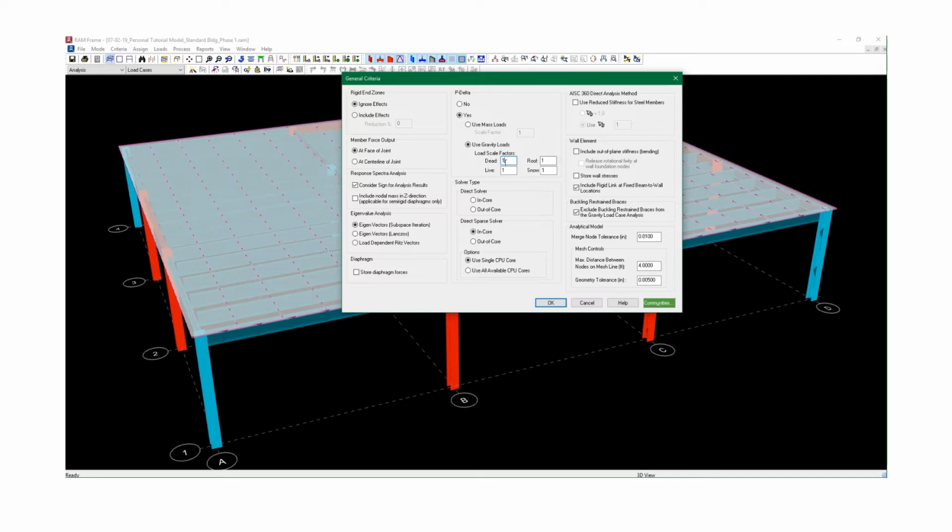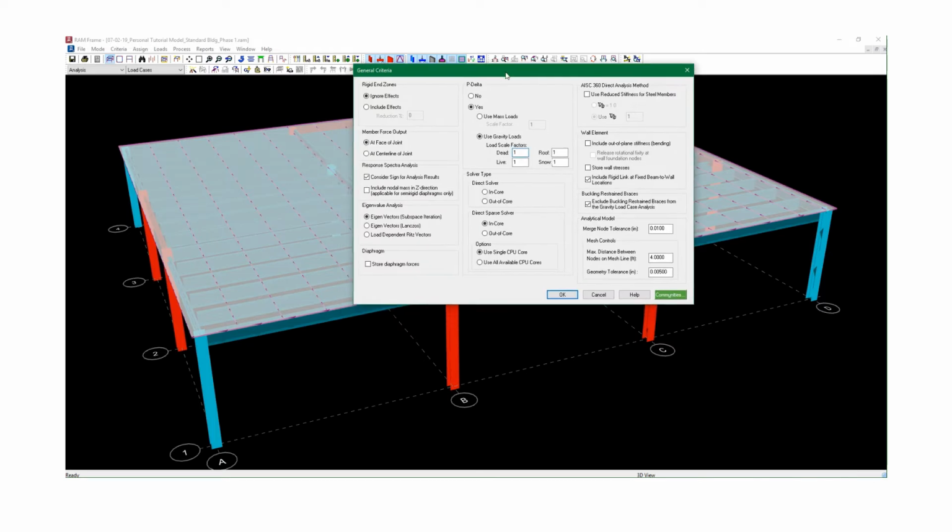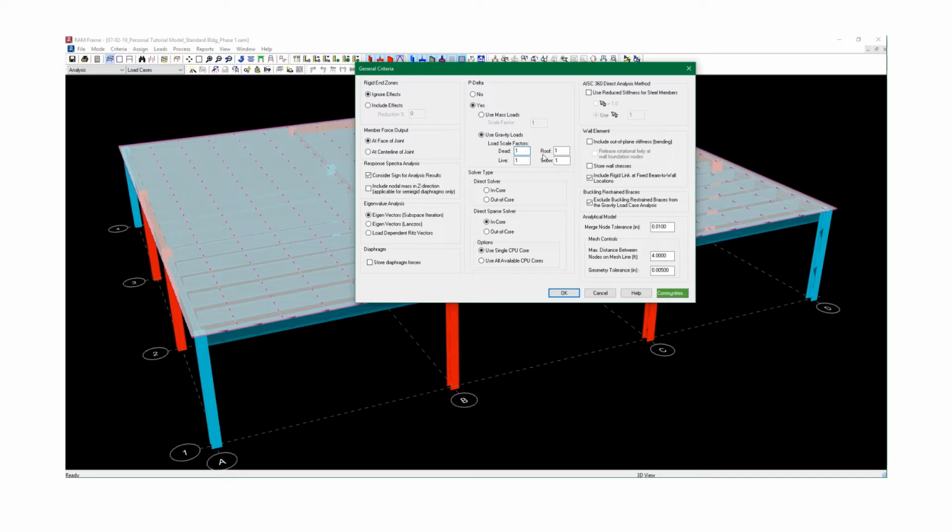However, these values are typically used as the LRFD method load factors, even though the engineer may be designing the structure using ASD methodology. So these load factors for the lateral load case that we're concerned with, earthquake and wind, the worst case scenario would be 1.2 for dead.